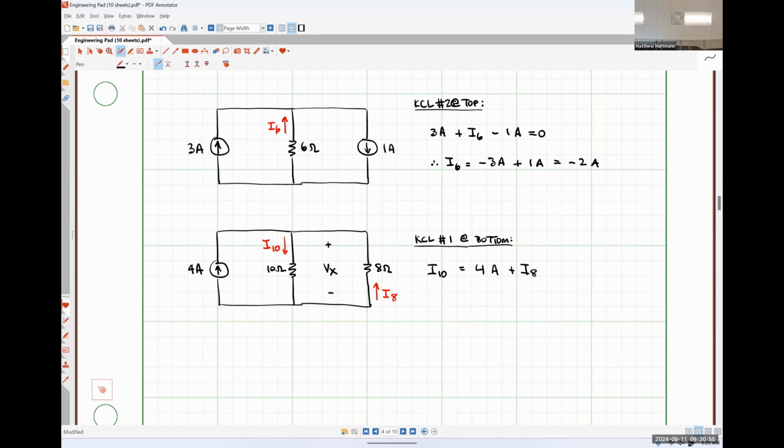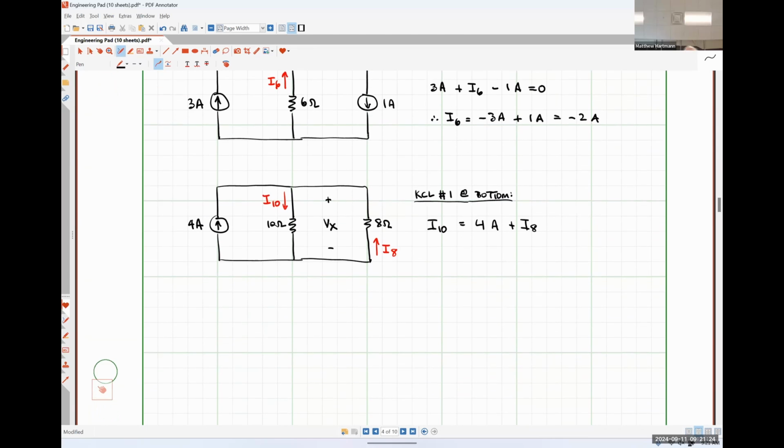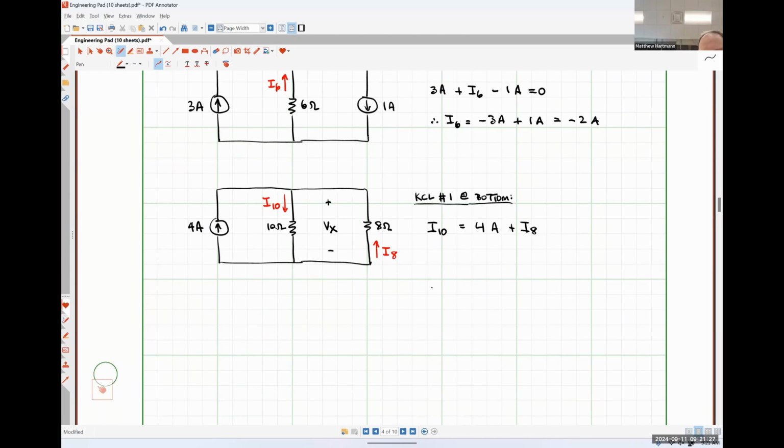So we have one equation and two unknowns, but we can put everything in terms of that voltage Vx because we just learned that when things are in parallel, they all have the same voltage drop across them, right? And it should be pretty darn easy for us to see here that everything is in parallel because we have what's called a single node pair circuit. That terminology is used a lot in your web work assignments. Anywhere you see single node pair circuit, above, below, whatever, just realize that means everything is in parallel. That's literally all it means. Okay? So using Ohm's law,